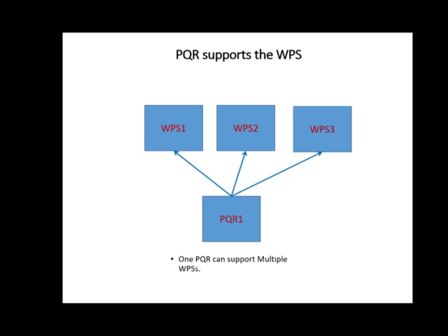So let's say customer number one, we're going to use WPS number one to make his component. Well, he only wants us to use 1/8 inch material, 1/8 inch 7018. Customer number two with WPS number two, he's like, I don't care. You can use 1/8 to 3/8. I don't really care. Do what you got to do. So have we changed anything? No. WPS number one just has tighter restrictions, but we haven't changed anything. The essential variables haven't changed.